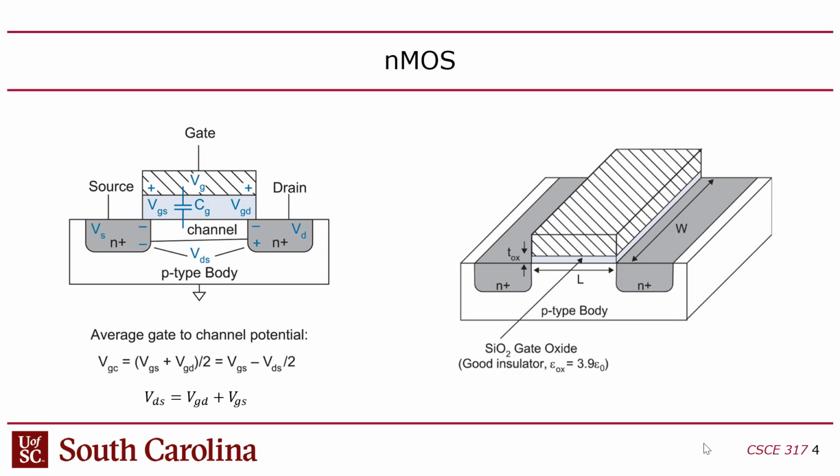What will end up happening is that initially the channel is just part of the substrate, right? Because it's just all one piece of bulk silicon. But once you start getting those electrons to collect in the channel, it is no longer equivalent to the substrate. They're now becoming decoupled. So when you measure the voltage of the gate, what are we measuring it to? To the channel, right?